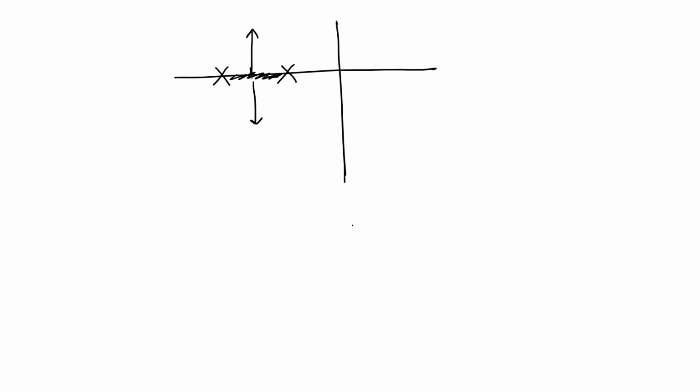Whenever there are two poles, and there exists a root locus branch between the two poles, then definitely there is a breakaway point. Similarly, when there are two zeros close to each other and there exists a root locus branch between them, then definitely there is a break-in point.